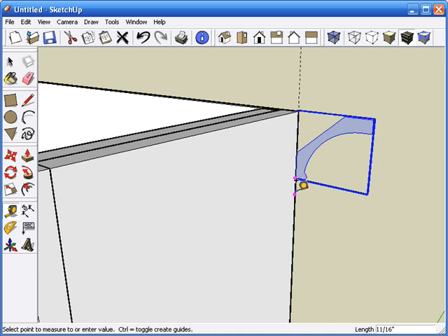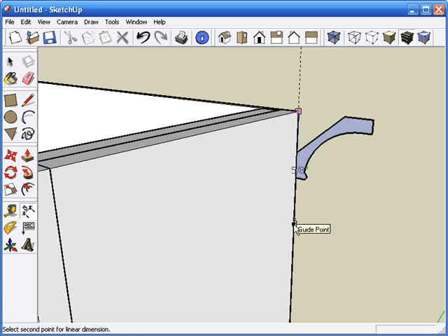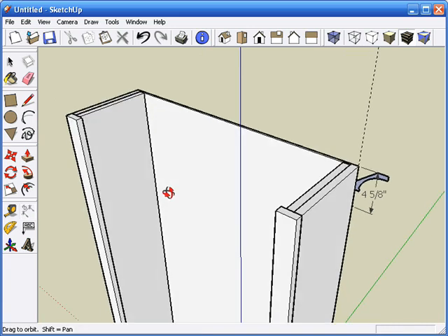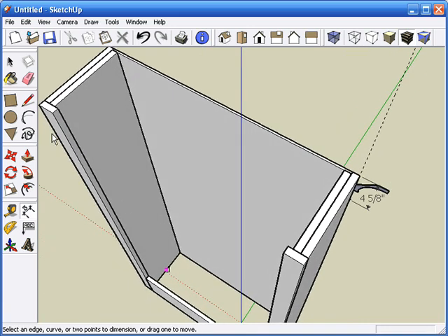Now let's come down again. I want to come down 2 inches more. So let's come down until there's 2 inches right there. So we'll make another click, and we'll get a little construction dot right there. Now how far is that? Well, we can use the dimension tool. This is the scale tool, and this is the dimension tool to actually read a dimension from those dots that we created. And that dimension is 4 5/8. So let's bring down the top rail 4 5/8.